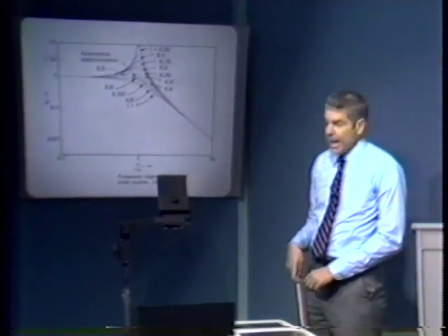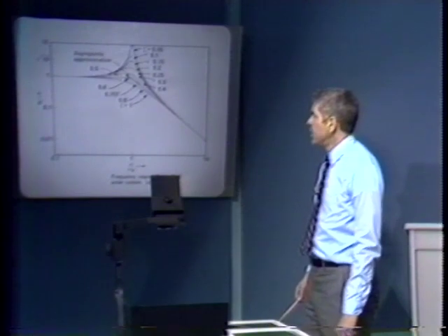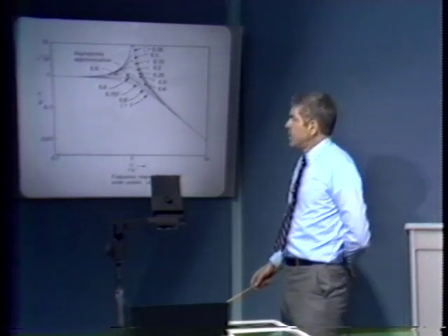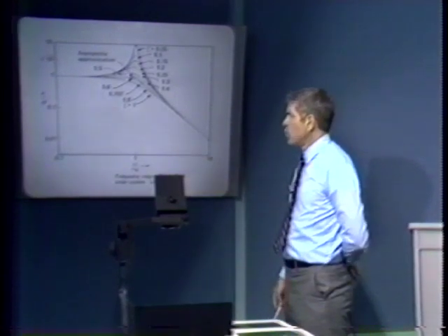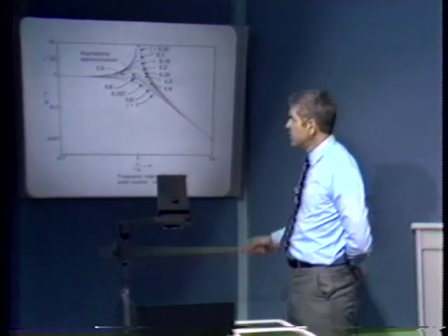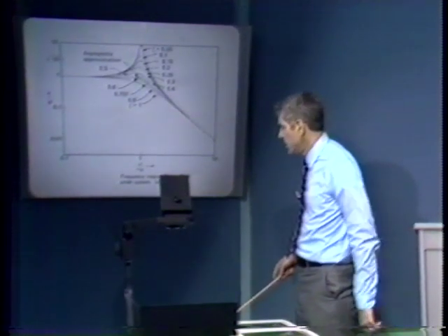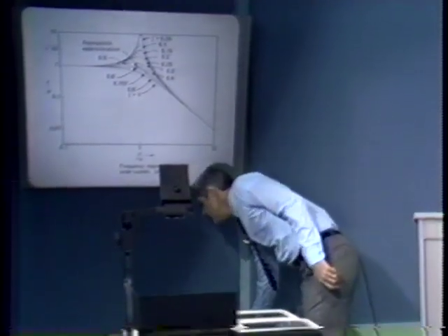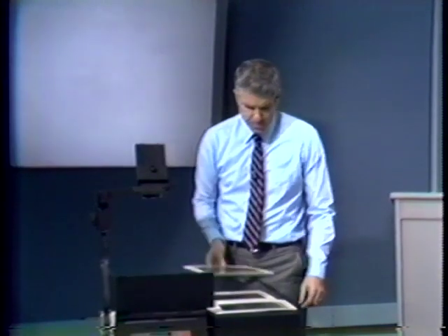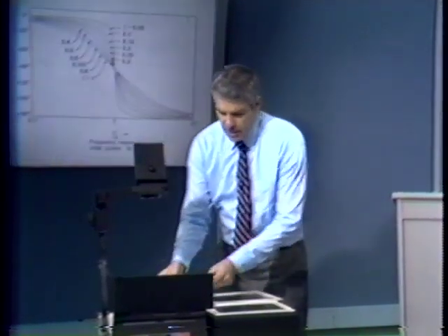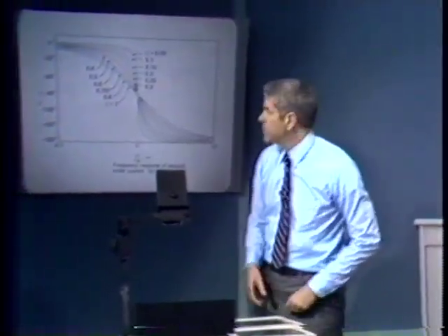We can also look at the angle associated with this plot. Usually for Bode plots, we have the angle and the magnitude on separate plots. In the first order one, we had them together. That wasn't very confusing. But on a plot that has this much detail, we can show things a little bit better if we keep the magnitude and the angle separate. And so here's the angle for our second order transfer function.